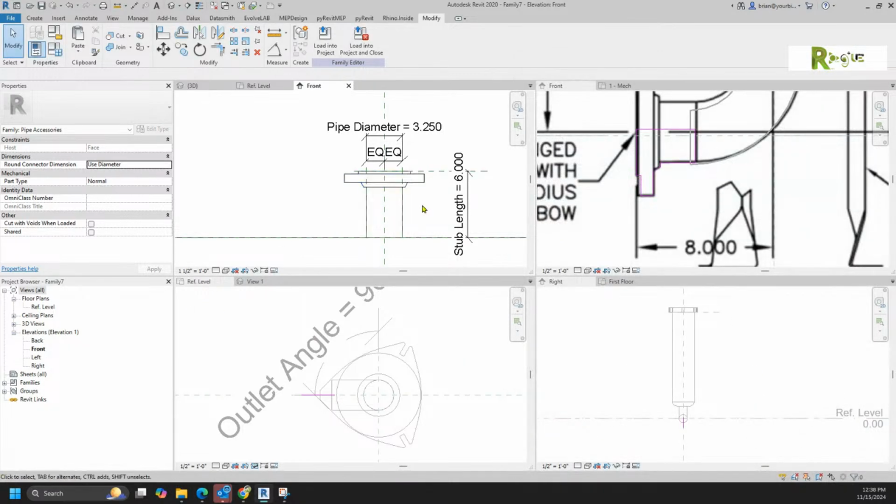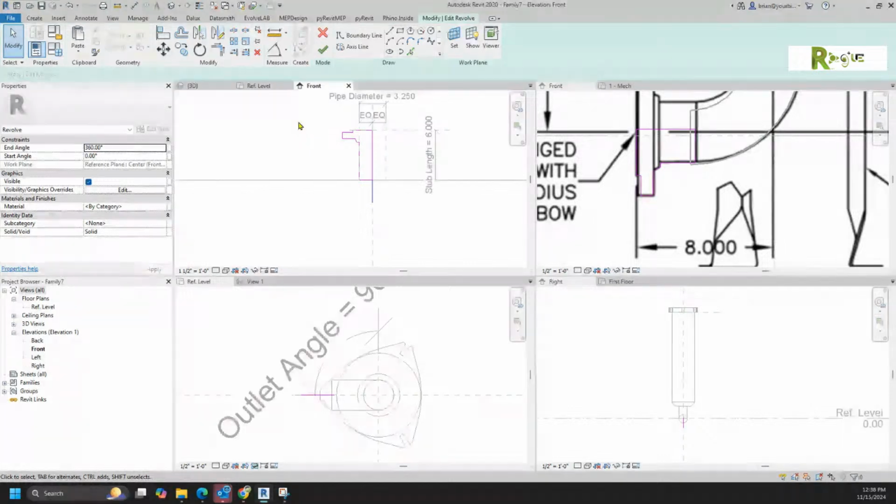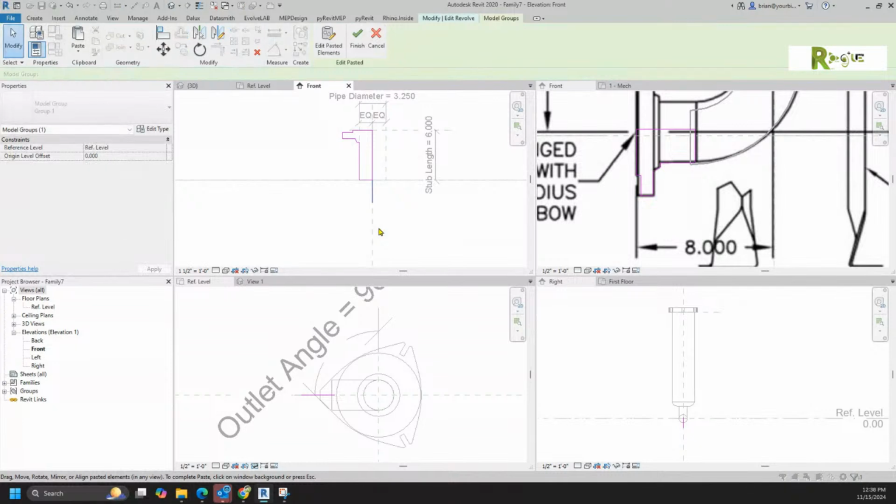And you'll notice, do you see how I drew the object and then I start to lay in some reference planes? If it doesn't take when you do that flex right there, sometimes what you'll have to do is take all of that pink stuff, do a Control X, a Control V, and then a 0. Don't ask me why, but if it doesn't attach it to those reference planes, that's what you want to do.